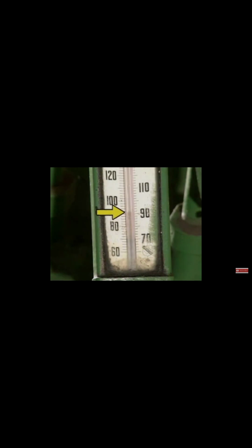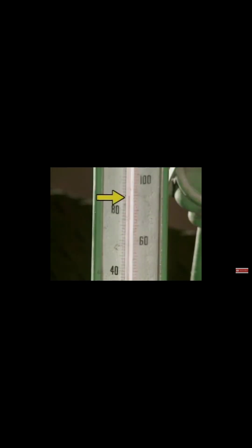Readings should be taken at the inlet and the outlet of the cooler to make sure that the cooler is operating properly. Oil temperature readings should also be taken at the supply and return lines. Oil temperature from the cooler to the bearing should be virtually constant. The temperature of return oil will vary depending on load, ambient temperature, and the specific bearing.